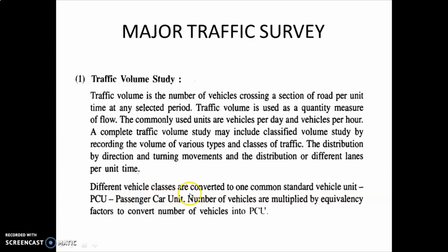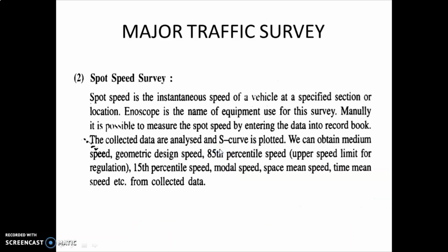Different vehicle classes are converted to one common standard vehicle unit, that is the PCU, which is called passenger car unit. The number of vehicles is multiplied by an equivalency factor to convert the number of vehicles into PCU. Okay, so this is all about the traffic volume study. Now the next one under the major traffic surveys is the spot speed survey.